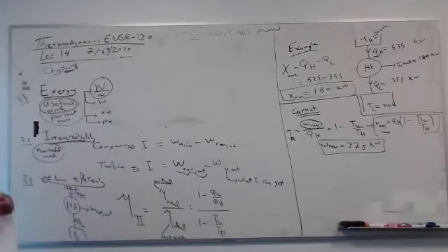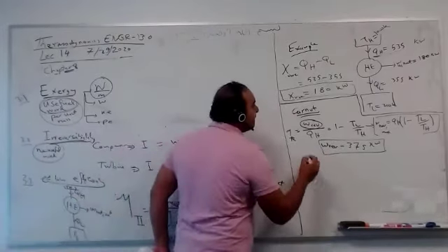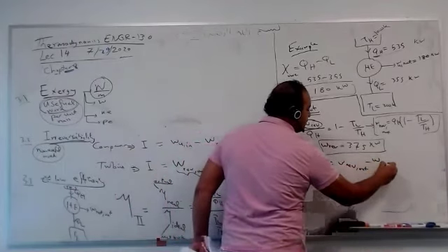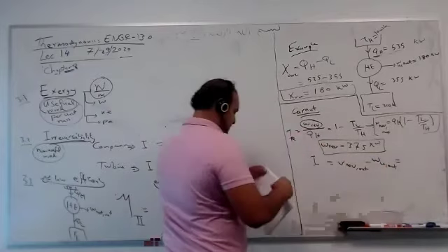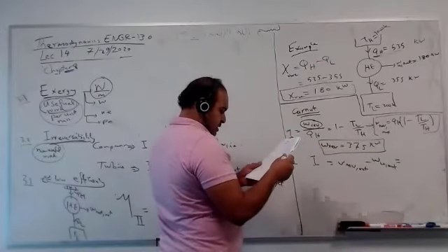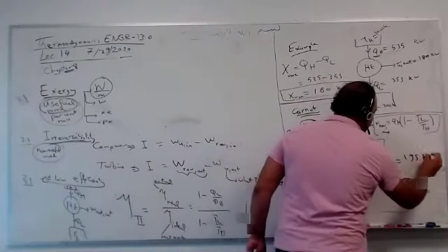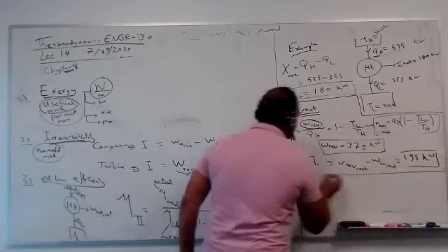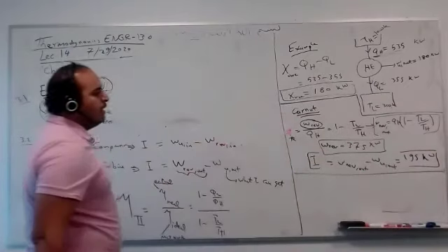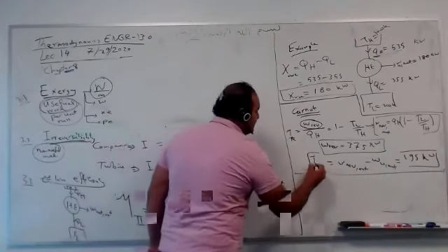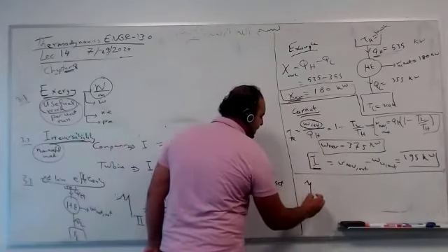Guys, does anyone not agree with this measurement or this equation? So irreversibility is W reversible out minus W useful out, which is this minus this, I don't know, 195. Oh, that's more than double. So I lost almost 50% of the work that I was supposed to get, 335. I get much lower than that. So this is the irreversibility. This is the exergy destroyed.